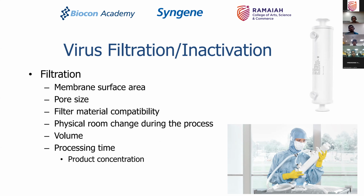Remember that if you have a virus which is present, the amount of care that you need to take in terms of environmental monitoring and in terms of personnel protection becomes very high. So in such a situation, you need to make sure that you contain the virus within a smaller processing area and not expose it to many large areas, because in case of any contamination, the decontamination process and the time taken will be large.